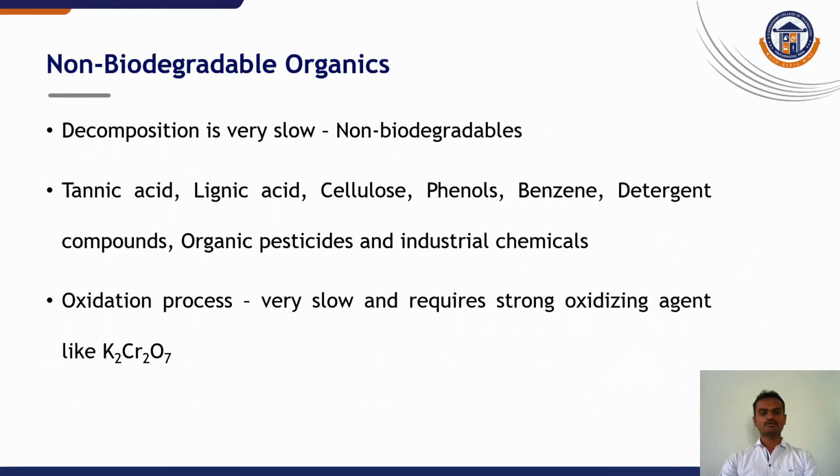The non-biodegradable organics are those that decompose very slowly or not at all under natural conditions. Example, tannic acid, lignic acid, phenols, detergents, organic pesticides, and industrial chemicals. These require strong oxidizing agents like potassium dichromate for breakdown, indicating their resistance to natural treatment processes.